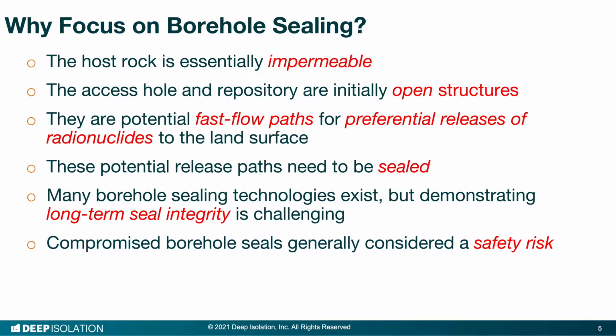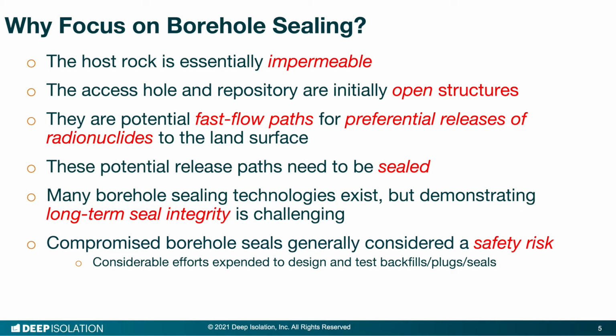Now, a borehole seal may not have been installed properly, or it may become ineffective with time because of chemical degradation and mechanical and thermal stresses. Borehole seals that are compromised in any way are generally considered a safety risk.